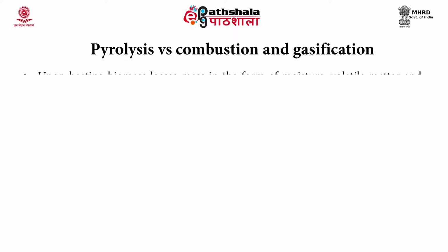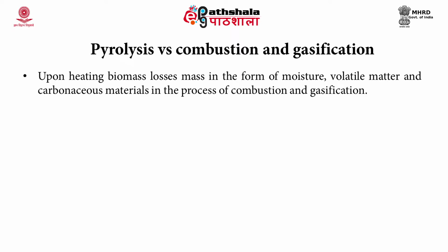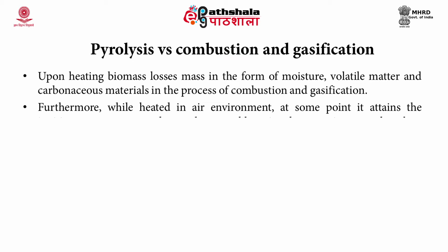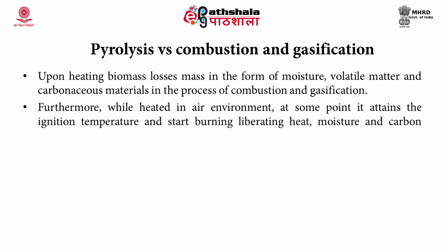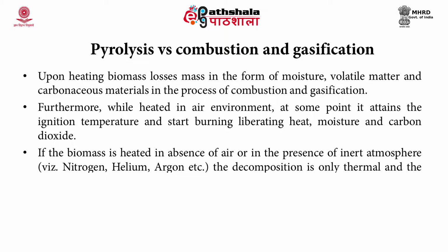Upon heating, biomass loses mass in the form of moisture, volatile matter and carbonaceous materials in the process of combustion and gasification. Further, while heated in an air environment, at some point it attains ignition temperature and starts burning, liberating heat, moisture and carbon dioxide. If the biomass is heated in the absence of air or in the presence of an inert atmosphere, that is nitrogen, helium, argon, etc., decomposition is only thermal and the process is known as pyrolysis.